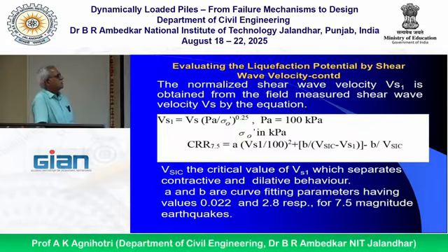So CRR 7.5 will be applicable to cone penetration test also, those curves are for 7.5 magnitude earthquake. So if your expected earthquake is of different magnitude, the value will be multiplied with MSF, magnitude scaling factor. Similarly, this equation is for CRR 7.5.